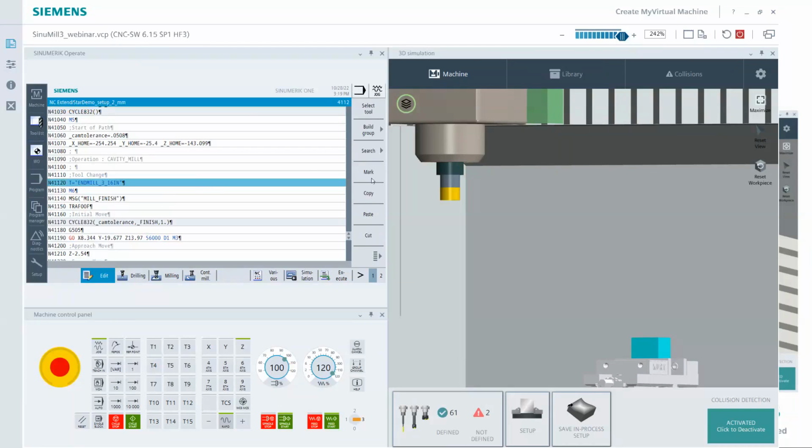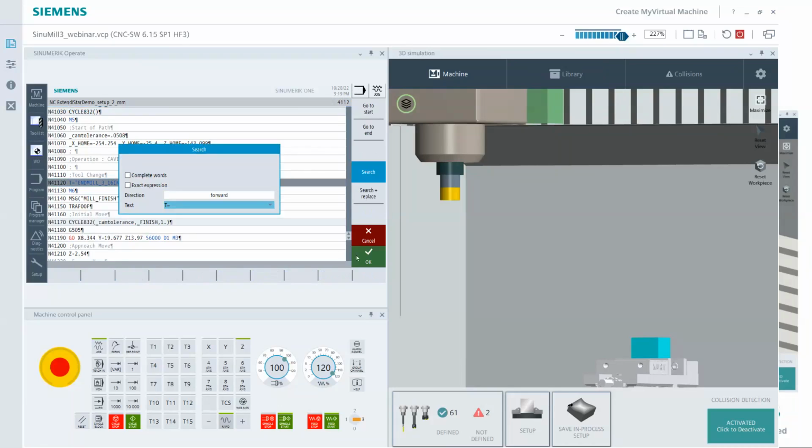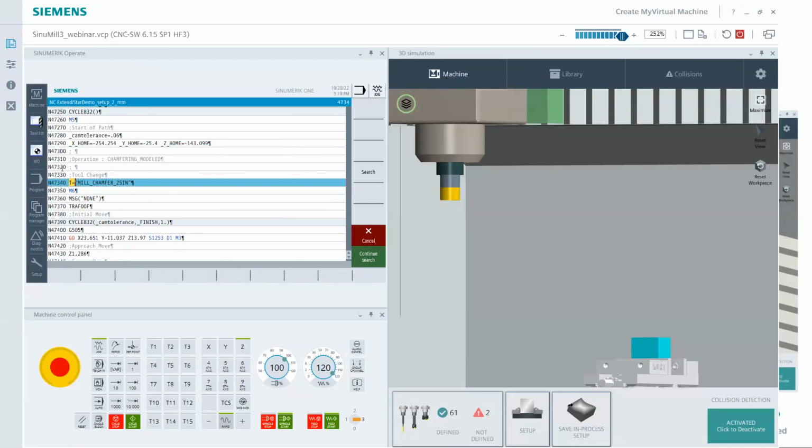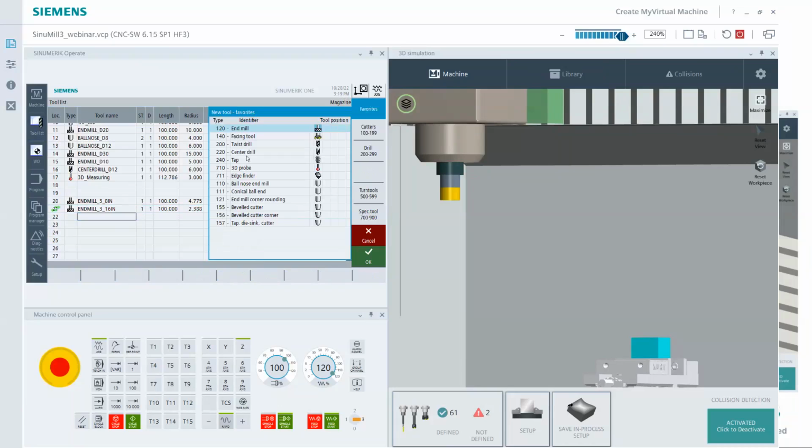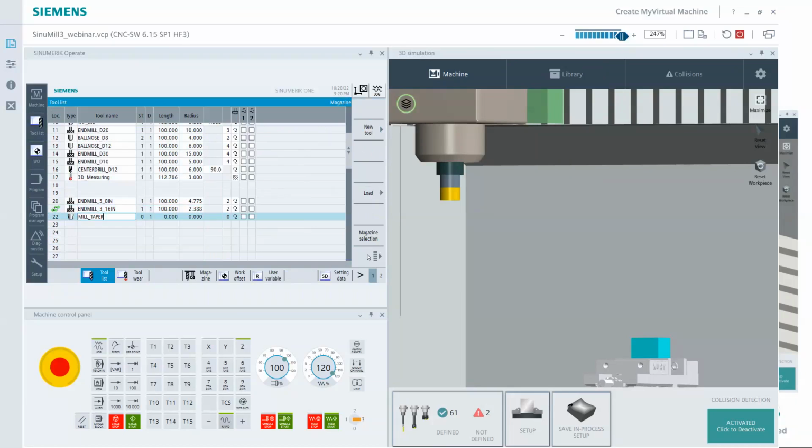So I'm going to show you how to create the chamfer mill as a tapered end mill, as opposed to, a lot of times we cheat and just use a center drill for a chamfer mill. But if I really want to have a controlled bottom flat, I can build it that way. So normally, like I said, a lot of times I'll do center drill for a quick chamfer mill. But if you do a bevel cutter, this is your tapered end mill. So here we can do this as our chamfer tool. Now, the trick there, give it some rough projection.